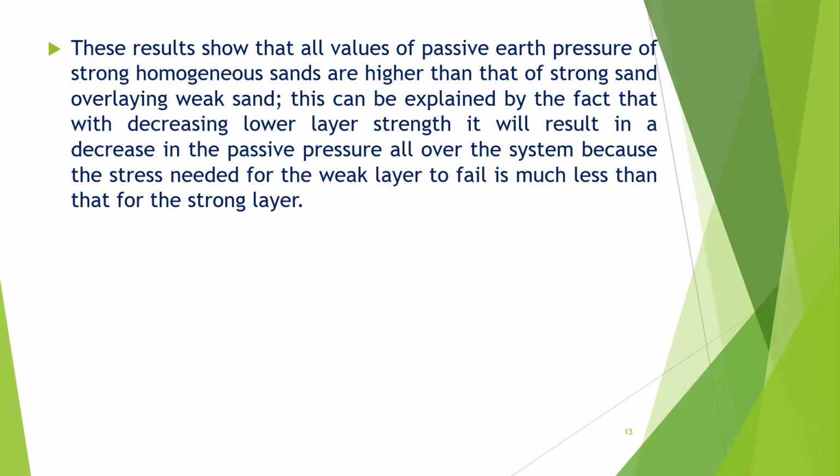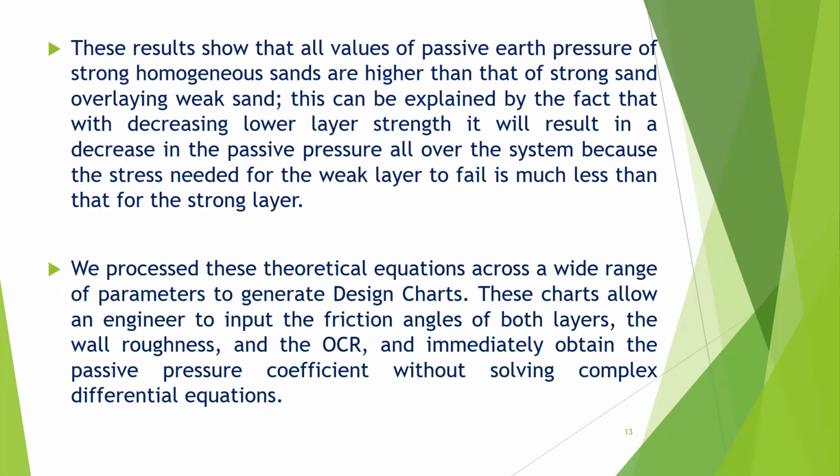This can be explained by the fact that decreasing lower layer strength will result in a decrease in the passive pressure over the whole system, because the stress needed for the weak layer to fail is much less than that for the strong layer.